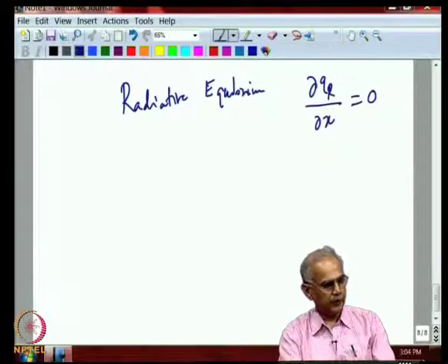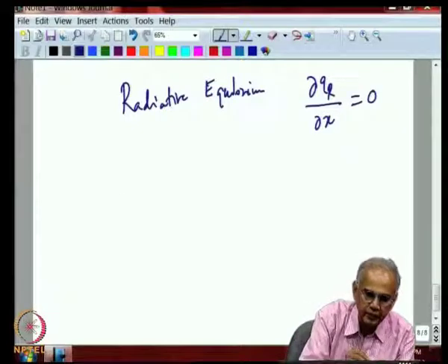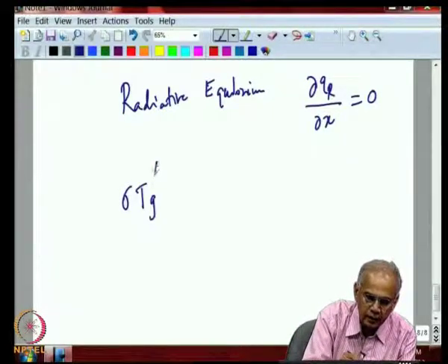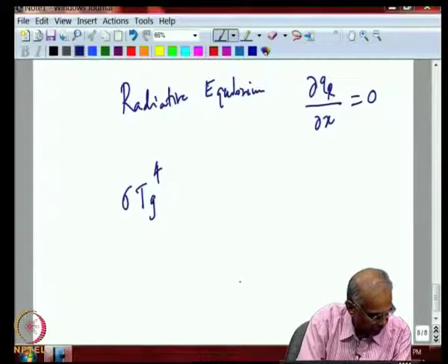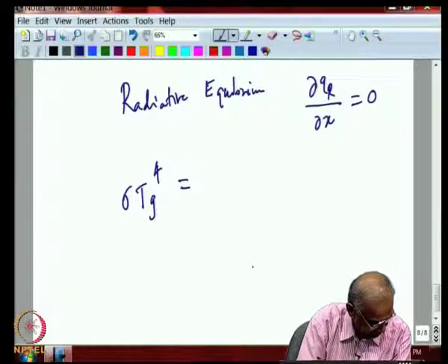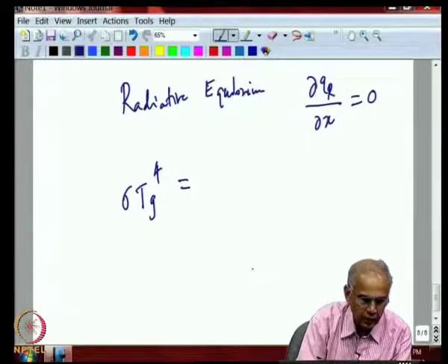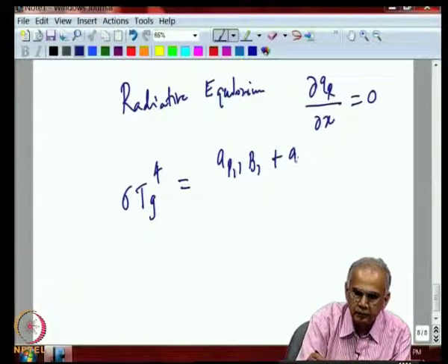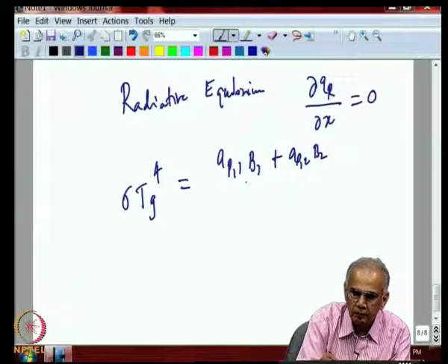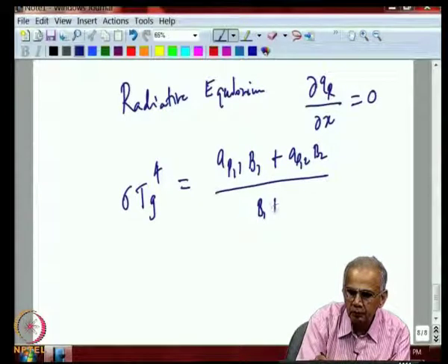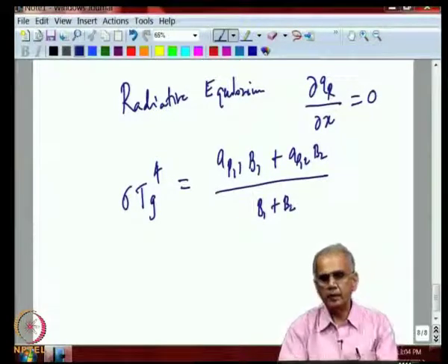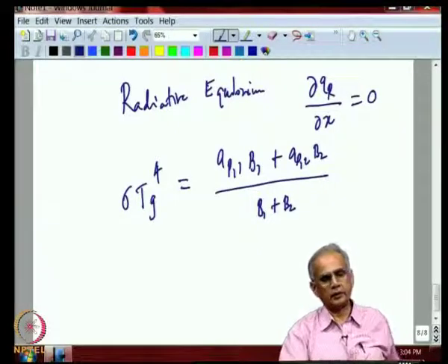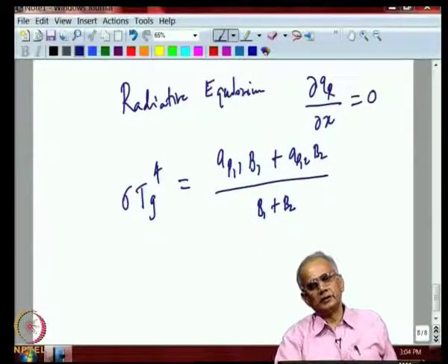So, for the case of the optically thin limit, this implies that the temperature of the gas in an enclosure in which you have invoked the optically thin limit will come out as a very simple expression for the temperature of the gas, because the equations are algebraic.